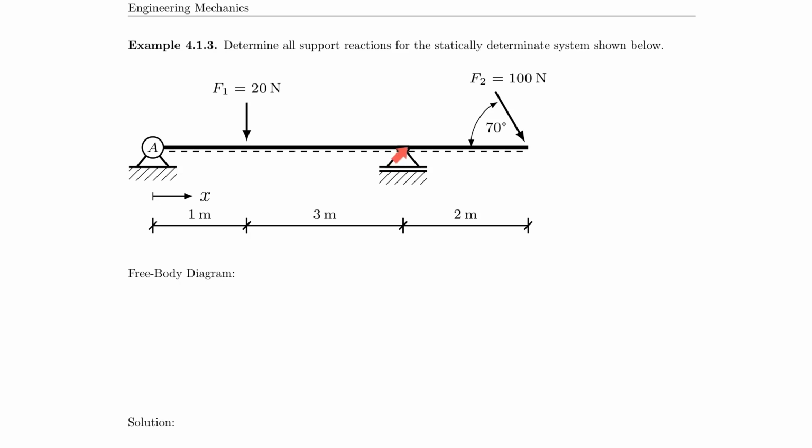So there's only a support underneath it and not in the beam. So we have the pin here on the left side, we have the roller or slider on the right side, and we have an overhang here, which makes the problem interesting because now you have to be careful in which direction it rotates. But let's take a look at it and draw the free body diagram real quick.